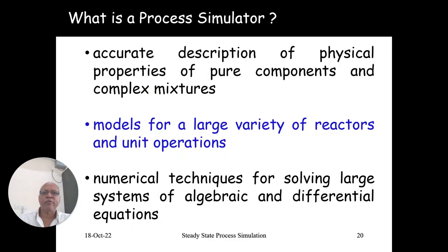So the advantage of a process simulator is you have accurate description of physical properties of pure components, and you will be able to estimate the properties of complex mixtures by using different property methods. You also have models for a large variety of reactors and unit operations, and depending on the complexity of the mathematical equations, even numerical methods are available to solve those equations all at one place.